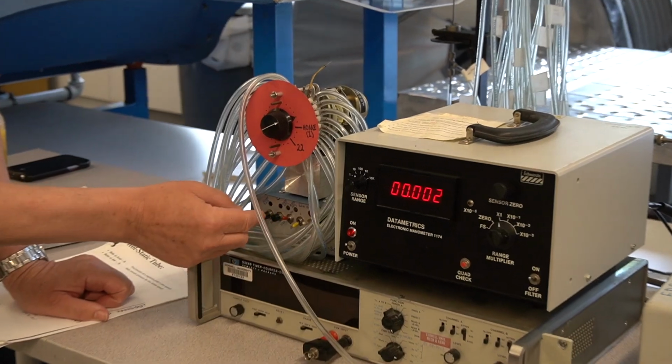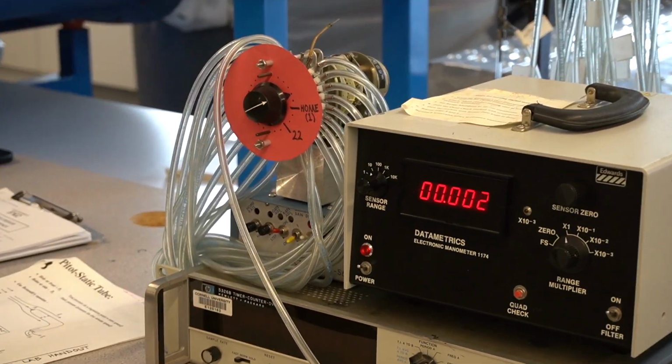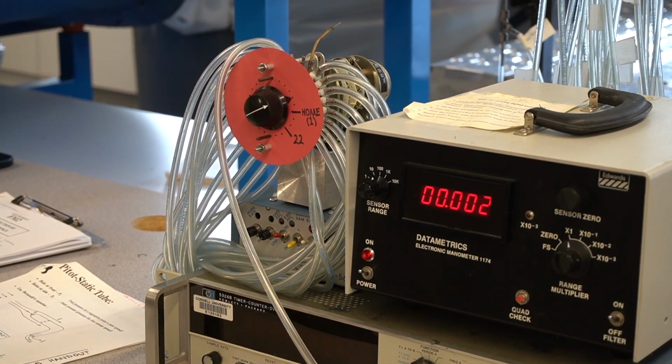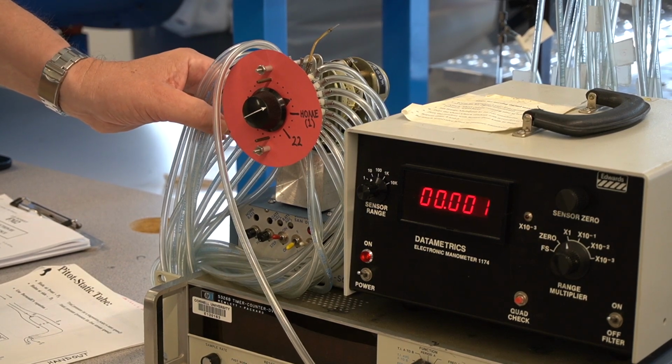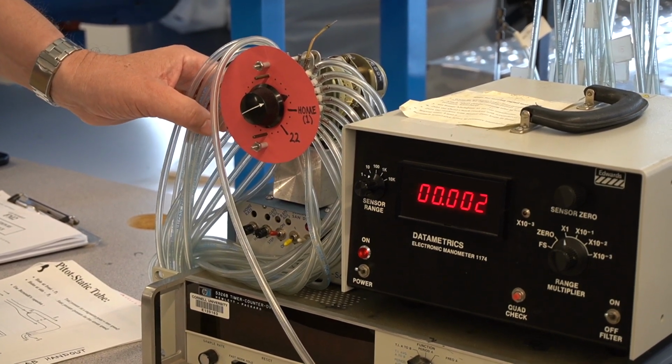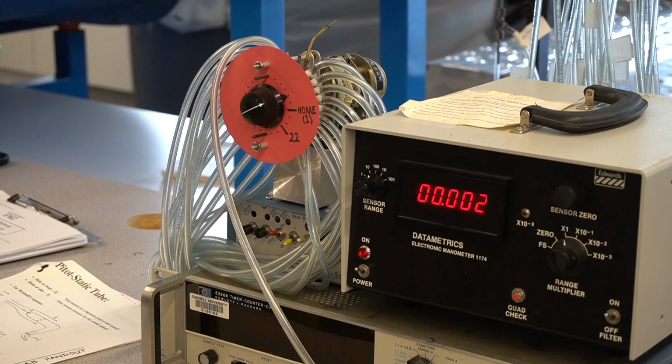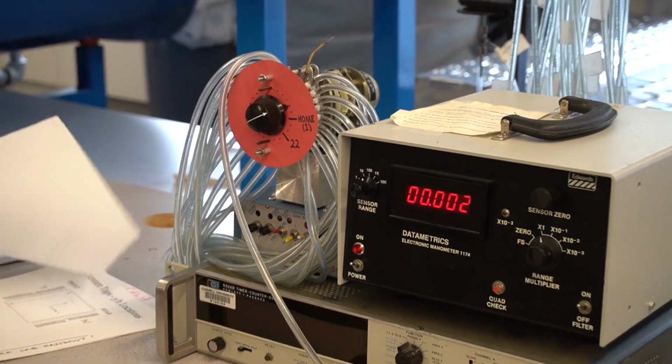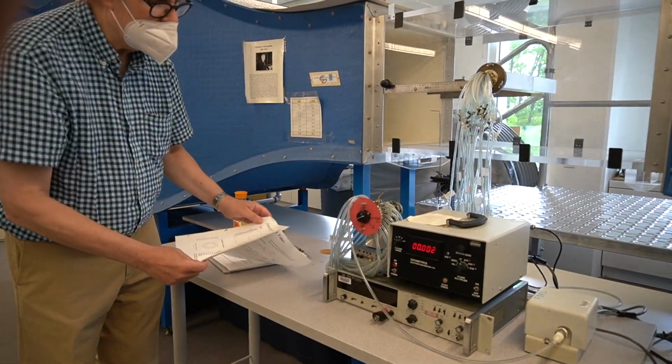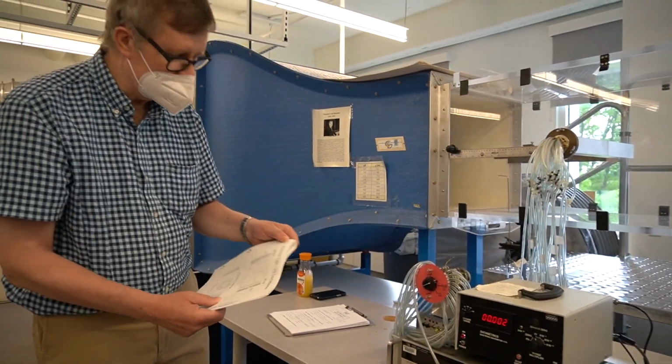I'm going to press this thing. So this thing turned one little increment, and now it's measuring the pressure at another one of these tubes in a different position. And so you end up measuring P minus PS, P at the point of interest minus PS, or PT minus PS. And eventually I'll show you how you get from that to pressure coefficient in just a minute.